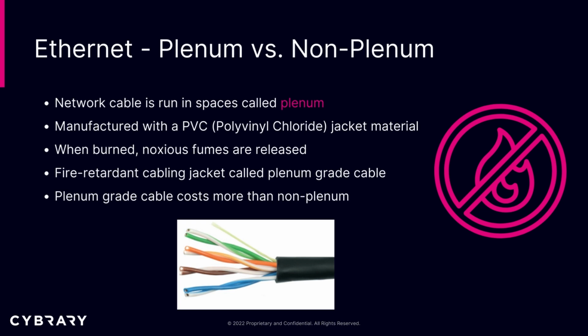So plenum grade cable costs a little bit more than non-plenum, and you would use these for specific places that call for a fire retardant cabling, such as in hospitals or medical offices, any places like that. Certain businesses require plenum cable as well.